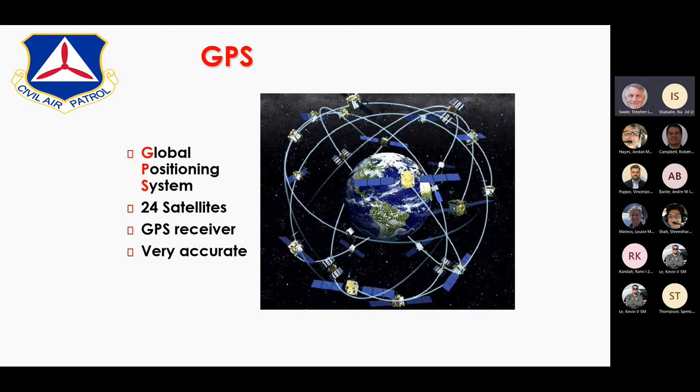GPS navigation relies on waypoints being entered, which makes it a real time hog for MOs. You can be buried in the cockpit punching in tedious numbers by twisting and turning knobs. You can end up accidentally putting in 1 or 2 wrong digits and you'll have a totally incorrect waypoint. So your method of inputting waypoints needs to be efficient.